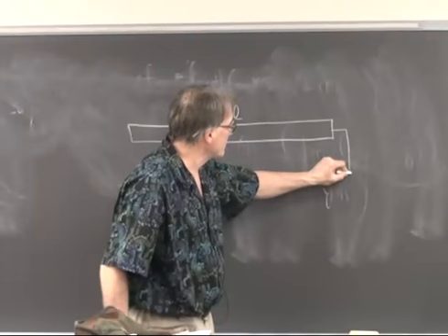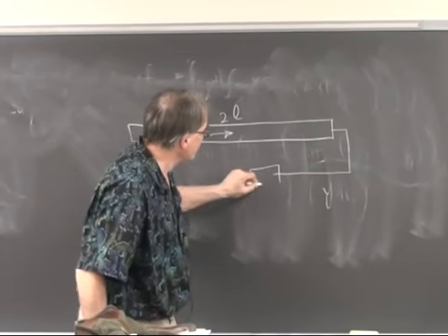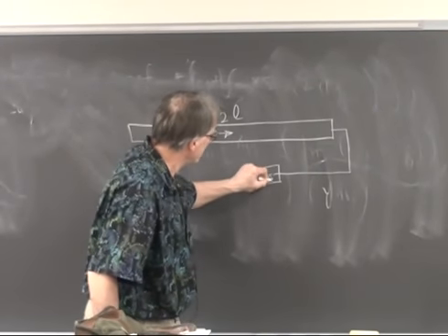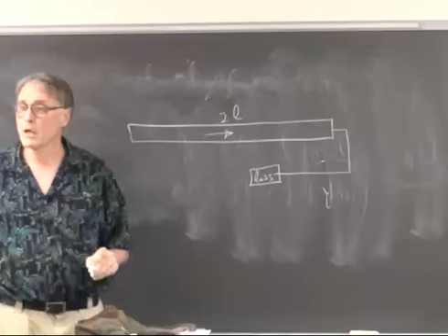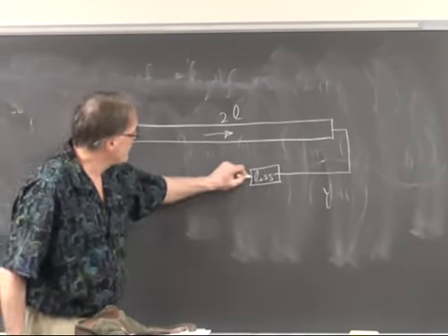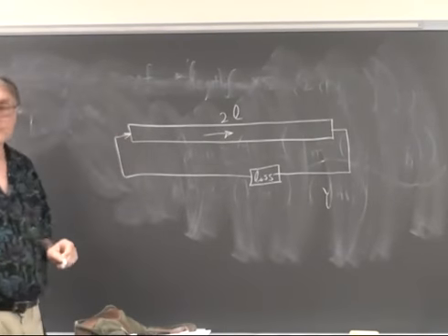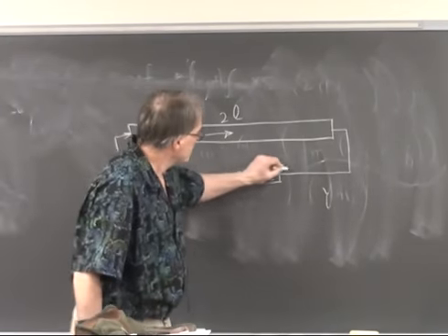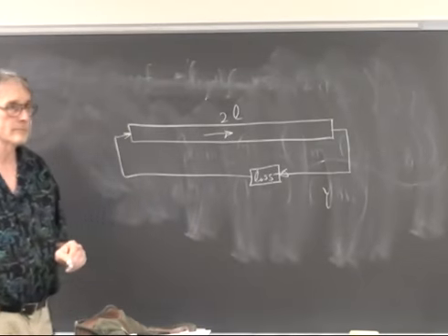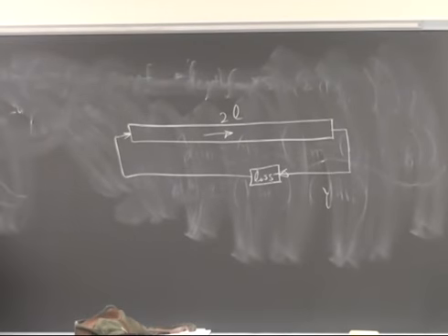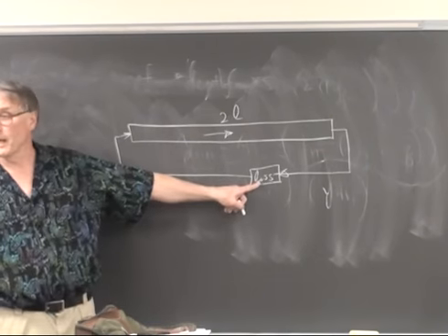We replace the loss with one loss element, which is 1 multiply, and then we feed it back into the input. Wow, that's really easy. That's a ring buffer in C. That's a ring buffer and 1 multiply.